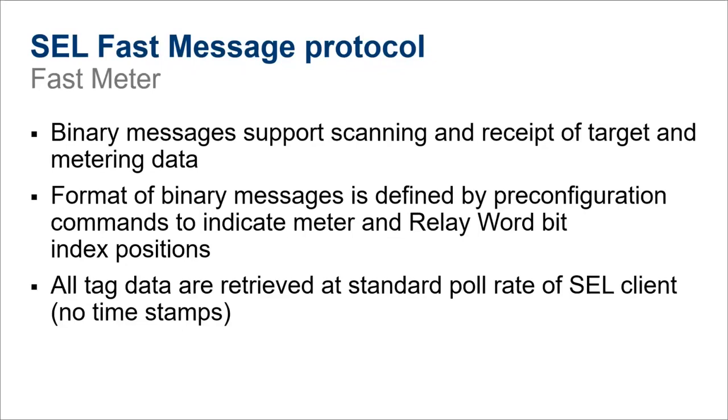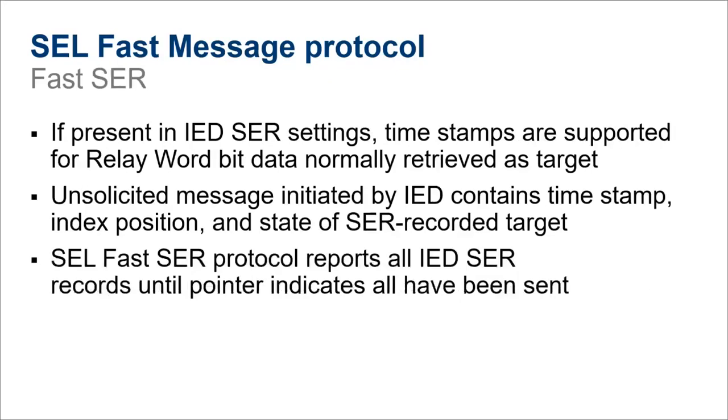And all tag data are retrieved at the standard poll rate. So if you have your client set to poll once per second, that's the fastest most data will be retrieved. And there will be no timestamp except what's applied at your SEL client. If you want that timestamp data, you can use Fast SER. So if it's present in the relay SER settings, timestamps are supported and will be retrieved along with normal target data.